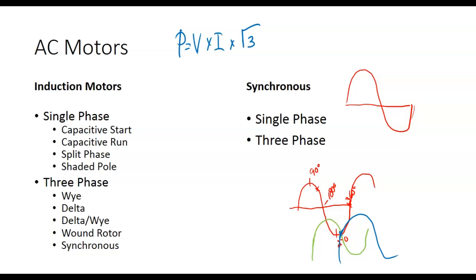We got to have how many anyway? 2. Okay. By adding one more conductor and using the difference between those, we don't have to run a ground, or common, on three phase delta. We don't have to run what we call a common. I can send 70.7% more power with just one more wire.